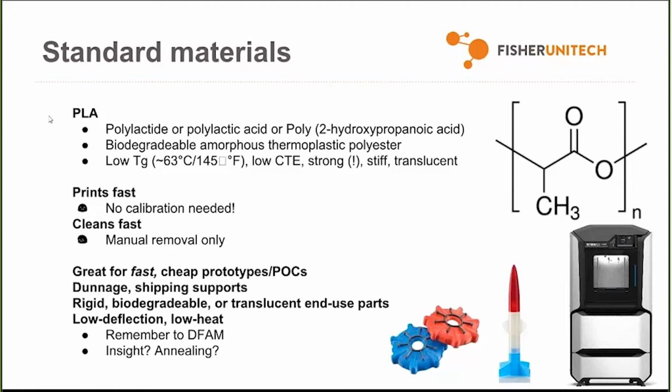And PLA happens to be stiff and very strong. Surprisingly, it's actually 40% stronger than ABS. So it's really not a bad choice for structural elements in low-stress applications like, for example, 3D printers. And I really think that is what enabled the RepRap movement. And that itself was a huge boon to the maker community in general, and that all has helped to bring 3D printers into the limelight. So I'm really glad that Stratasys has embraced PLA in the F123 series of printers.